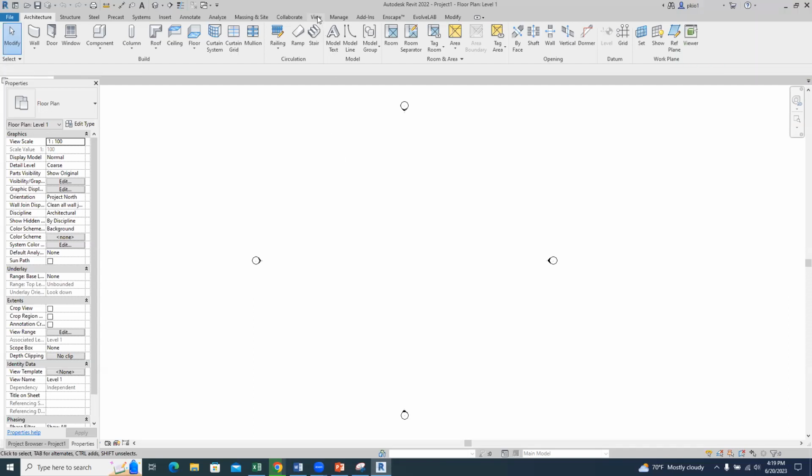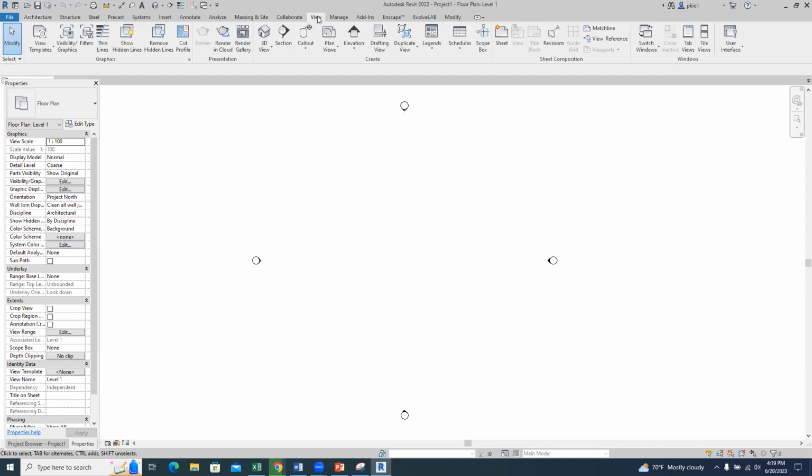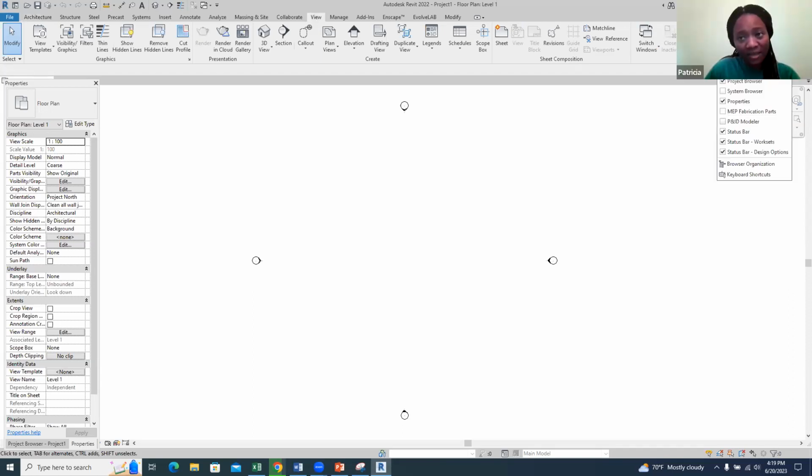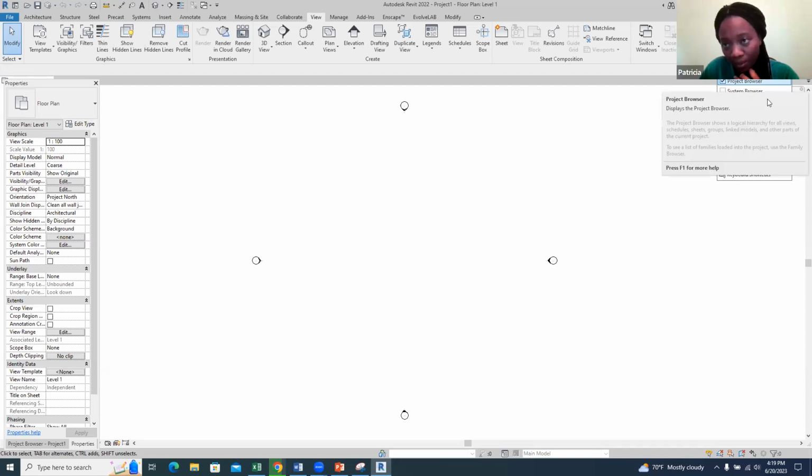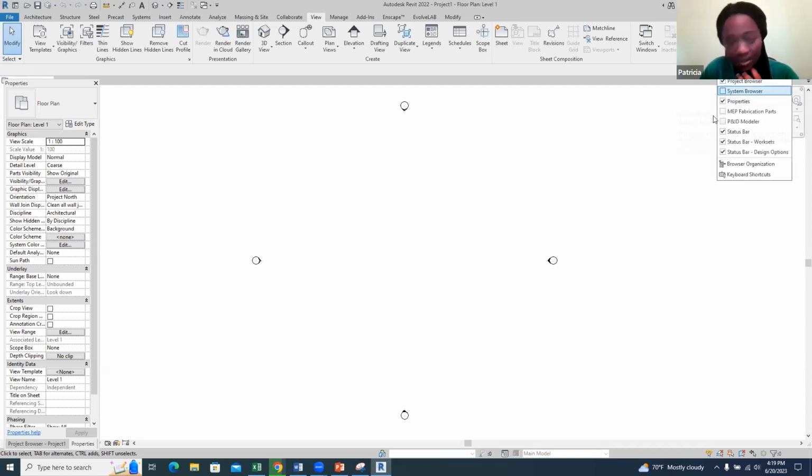Okay, so you go to View, and then User Interface. You can select the boxes that are checked. You see that my Project Browser is on, my Properties is on. Make sure that they are ticked so that they will also show on the screen.